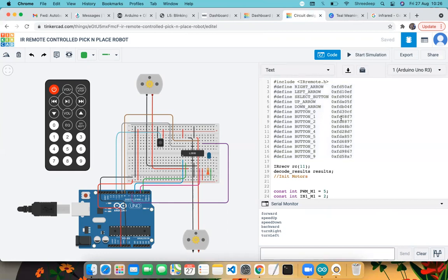That means the right arrow means 5058 FD101F. These are the standard codes available for every button, including the alphanumeric values, again set by the standard committee. So the IR remote provides those values. The IR remote is nothing but a microcontroller based application: once you press a push button, it generates a code from the microcontroller and sends the code through the IR emitter, or IR transmitter.